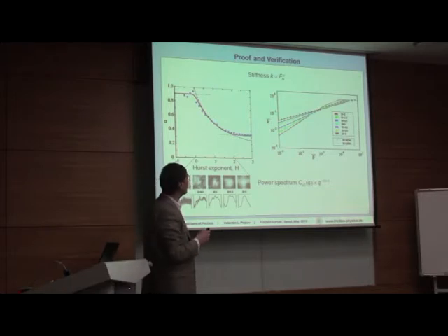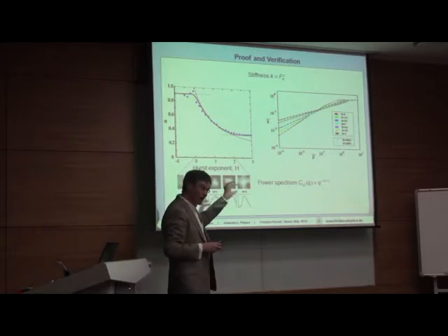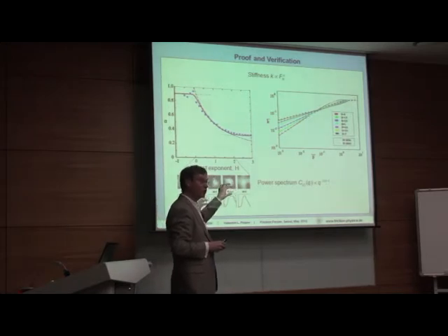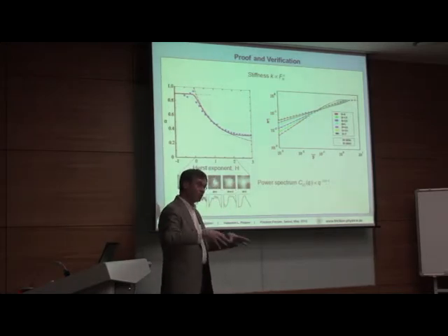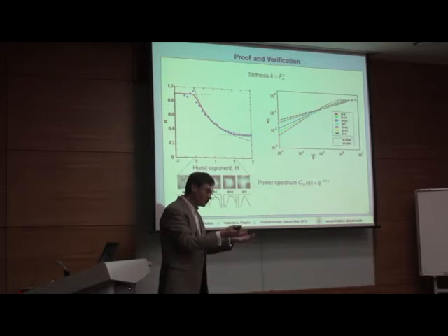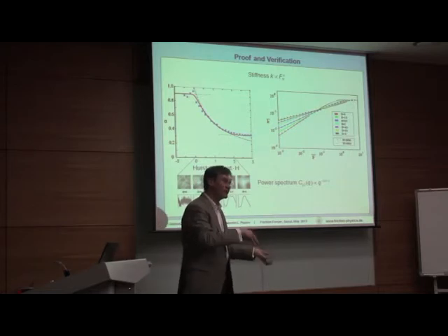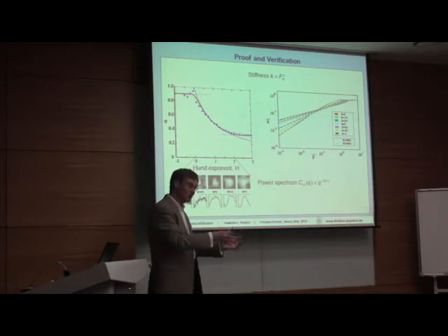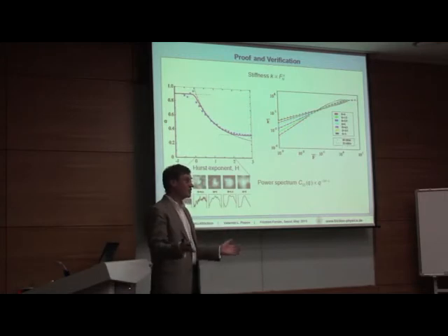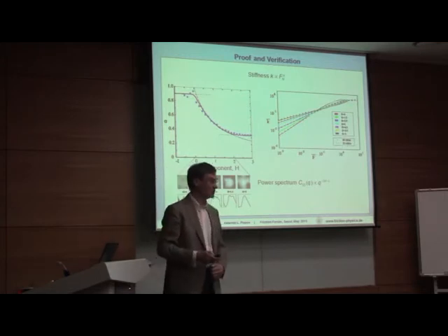Of course, the method is not applicable only to self-affine surfaces. If you have a more complicated spectrum, you can still use it. It is just as for forms: the simple rules for the bodies of revolution are for power functions, but if you have any form, you can still recalculate. The same for rough surfaces. There are simple rules, multiply with q, if you have self-affine. It is a more complicated integral transformation if you have just a rough surface, but it still works.